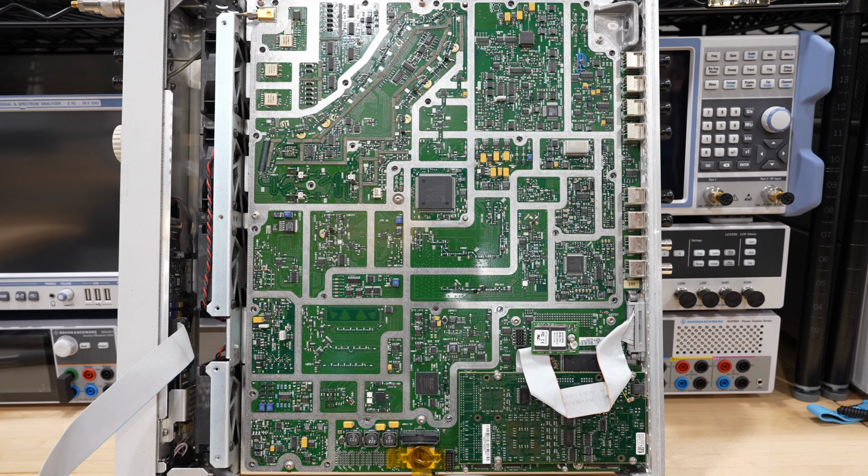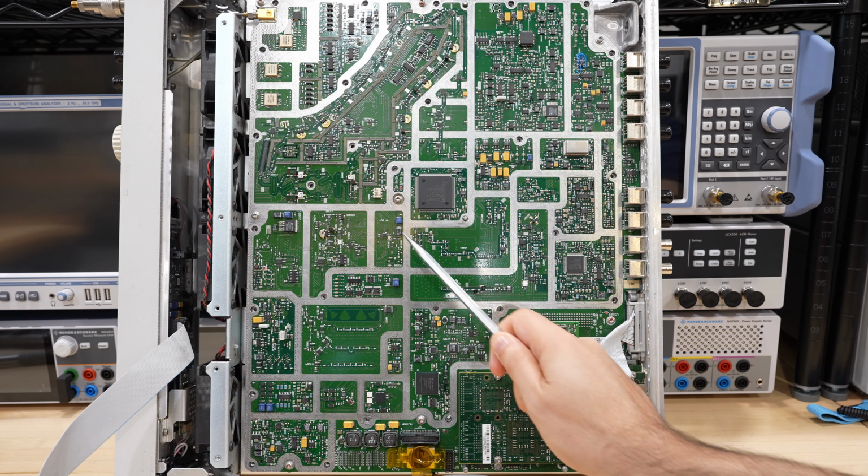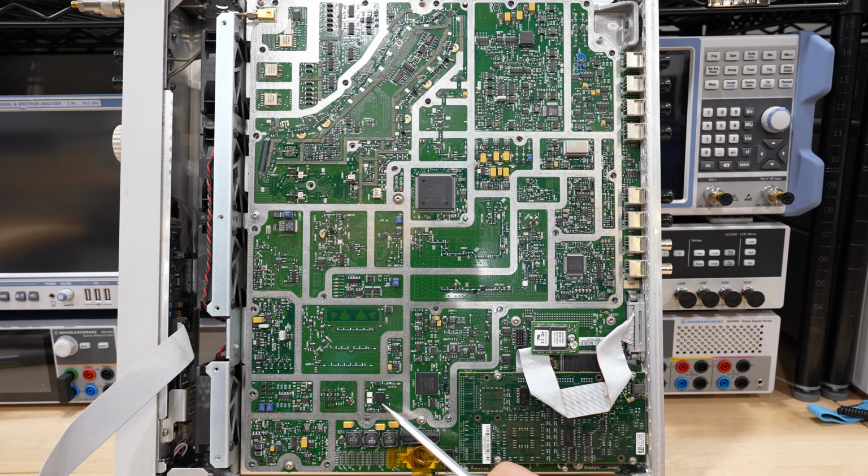The portion that we need to pay attention to is where the VCO is, because that's the fractional-N loop around it. If you look very carefully, and I'm going to zoom in so we can talk about it in more detail, our VCO is right over here. This little section is our VCO with discrete components, that amplification area right after it, and then the signal is fed through here and then finds its way back through this section. And here is our fractional-N divider, here's our phase detector, and then back in here to control the VCO. This FPGA is controlling this. The combination of this guy, this guy, this guy, and the loop makes the fractional-N PLL.